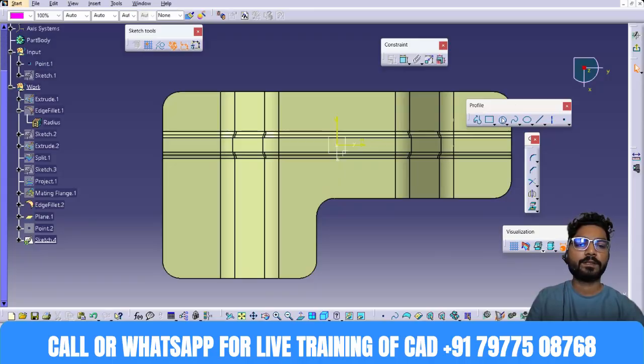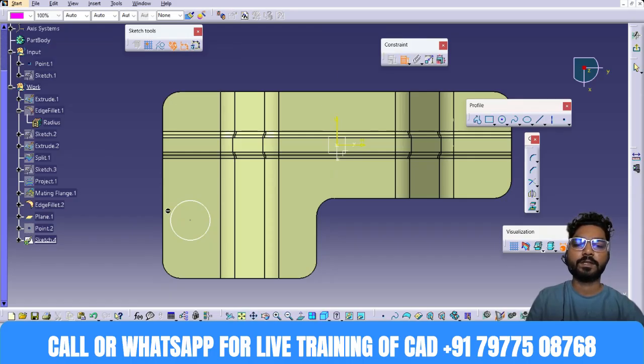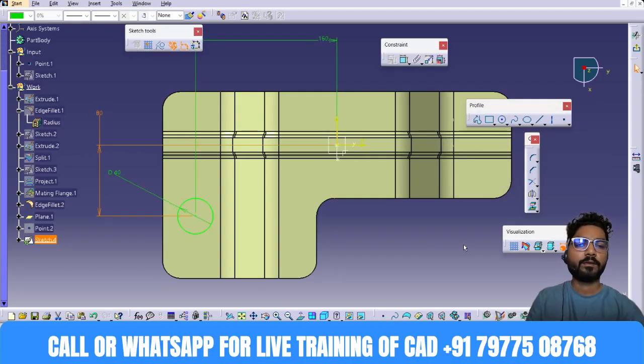So let's suppose here I want that flat fixing area. So here I'll apply the diameter, and you can give the dimension. So it is parametric, you can move the position later, right? So this is 160 I will keep, and this is 80 I will keep, let's suppose. And now exit.